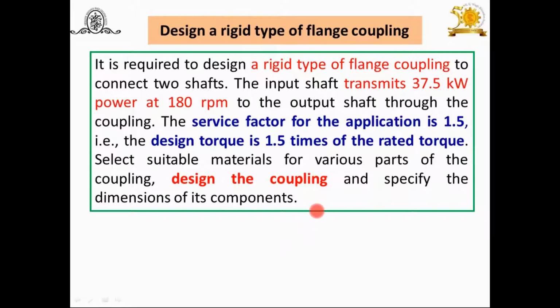Why? It's an open-end problem. Open-end means, first of all, we have to select the material, then its properties, then FOS, then find out the permissible stresses, and then we will proceed. But in an examination or university examination, you will find all the data may be available to you. You can refer to that data and accordingly solve this.